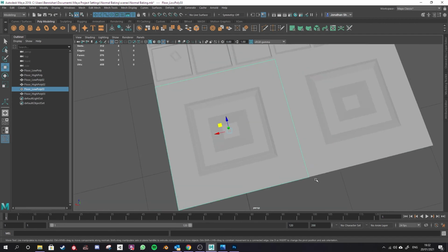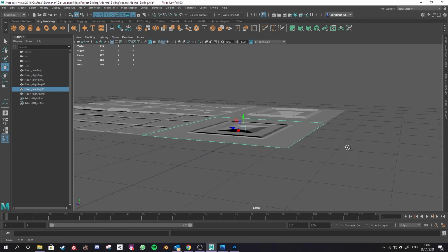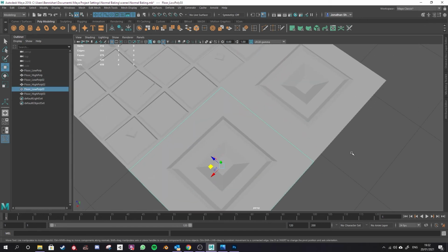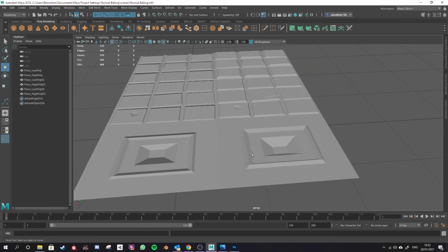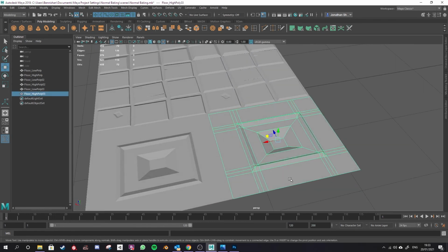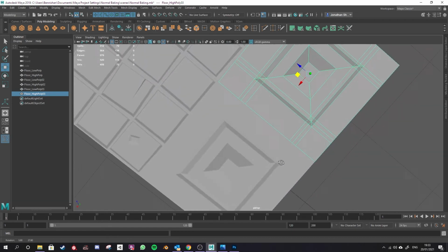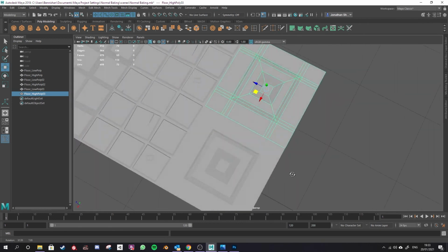So this works quite well with what we've got here, but you can see definitely at a high angle that it is indeed flat compared to this, where you see the bottom of that object actually slopes down in. So there's limited use to normal maps. Whenever your geometry is sticking out a lot, or if it's impressed a lot like it is here, you're generally better to add some extra geometry in and then bake the little details. So there are limits to normal maps. I just wanted to show what they could do in Maya and some of their limitations.